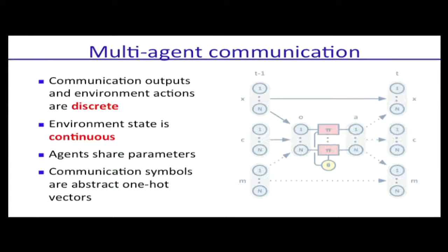The reward function we use here is a continuous reward function that penalizes for square distance from goals that you're supposed to achieve. And the optimization we're running here, the reinforcement learning, is with backpropagation through time. You saw this back in Sergey's early lectures, and then again in John's lectures a little later, that you can do reinforcement learning. If you have a dynamics model, which we assume here, then you can backpropagate through time. And if you have a reward function shaped like a quadratic distance from a goal, you can backpropagate the effect of the reward and see how to change your path and your communication to do better.